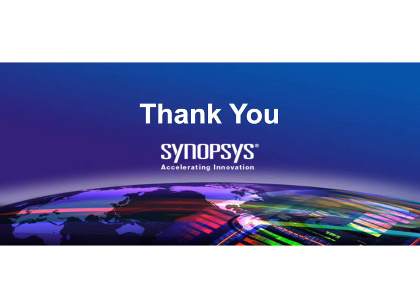All right, thank you, Yervant. Our next question for you: does this memory solution allow the user to apply new algorithms, or are the algorithms hard-coded in the RTL IP? They are both, in fact. So you can do both. The FinFET algorithms are the algorithms that we provide through our yield accelerator, which is the tool that sits outside the chip. That is the software with a library of algorithms. Now, those algorithms, you can either program them in advance, and we have the ability to do that, and hardwire them in advance in the chip, and in that case you don't need to ship them later. Or you can keep short default algorithms in the chip, but augment them with the FinFET test segments that are sitting outside in your software. So you have the ability to put it either inside the chip from the beginning, make it part of your design, or scan them in and program the engine later on, post-silicon. Both are possible.